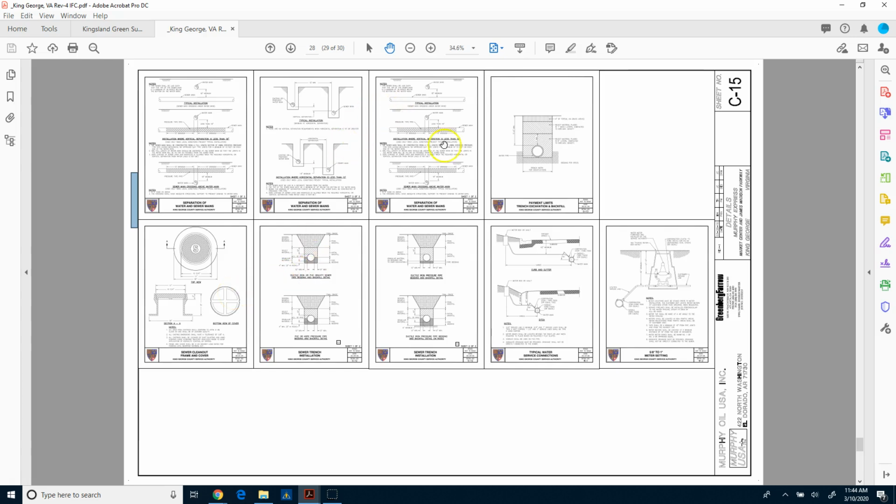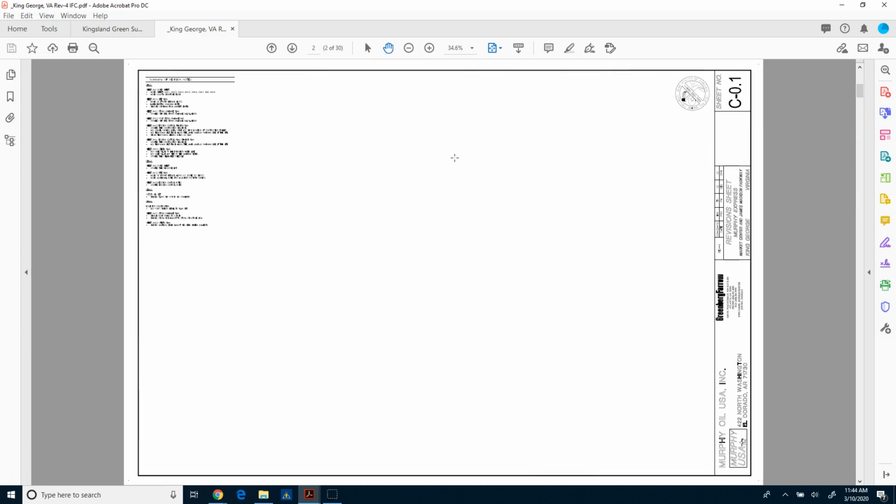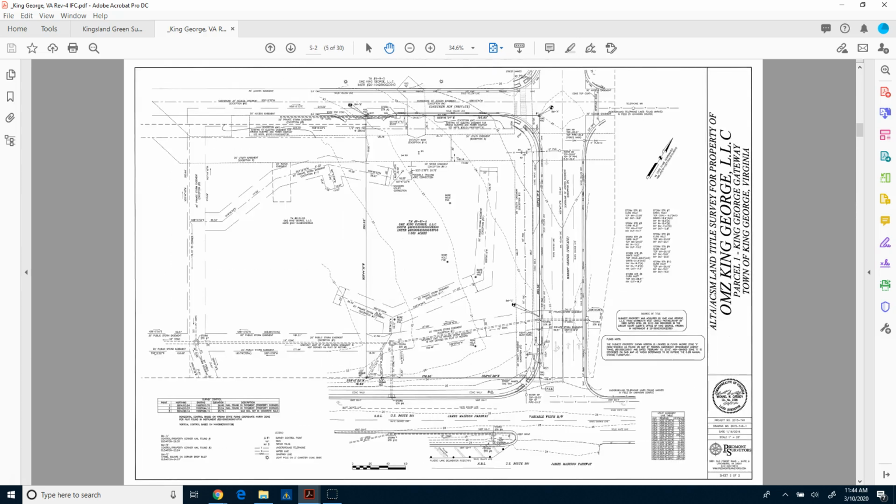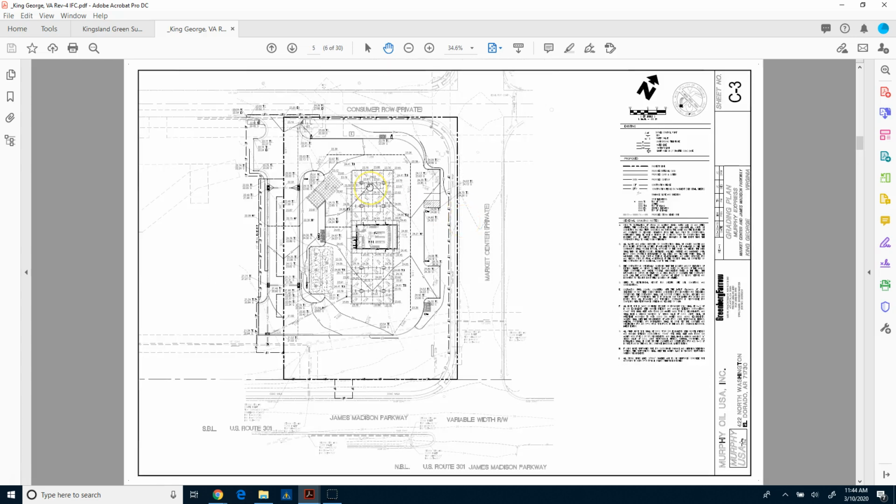Now, I could use this entire set of plans to build this model. It would be advantageous, obviously, to have the CAD data, but I could use the combination of the layout plan and the grading plan to build whatever model I need. It's going to depend on how the contractor is going to use it, whether it's off machine equipment or on machine equipment, whether he's using laser for grading the pad, since it is a relatively flat pad. That might be the course that they go with, but the data and understanding how to find that data on the plan sets would be advantageous.